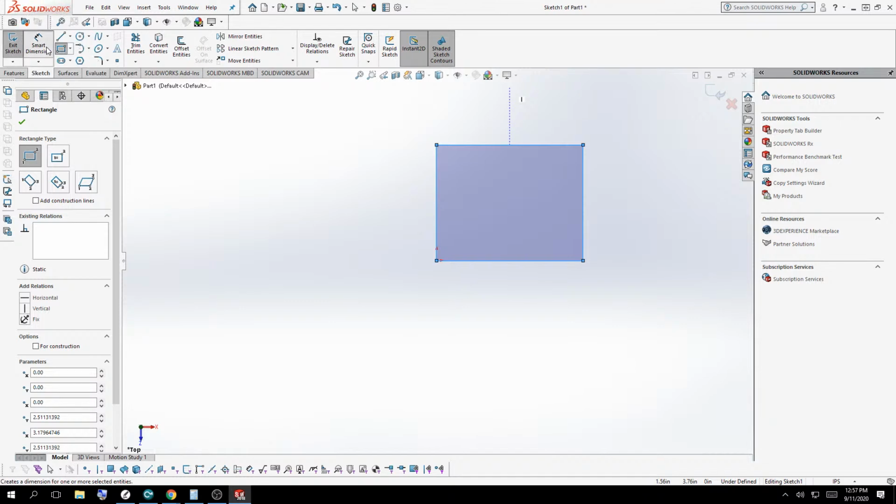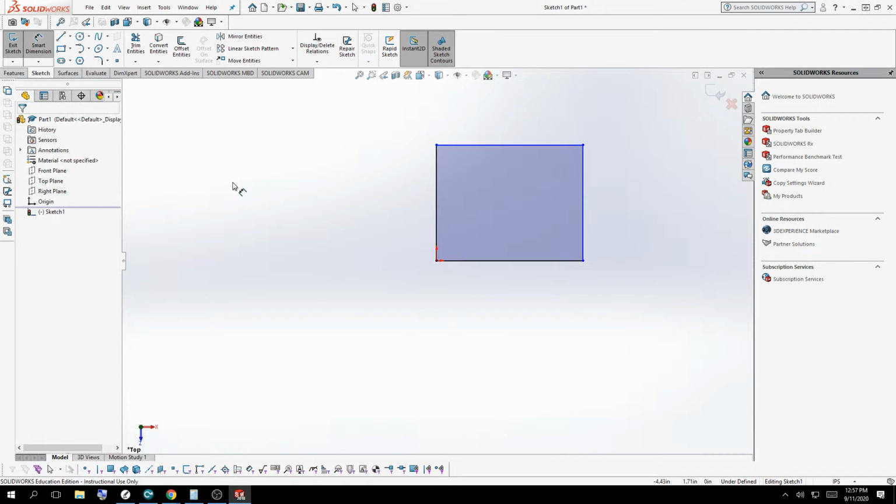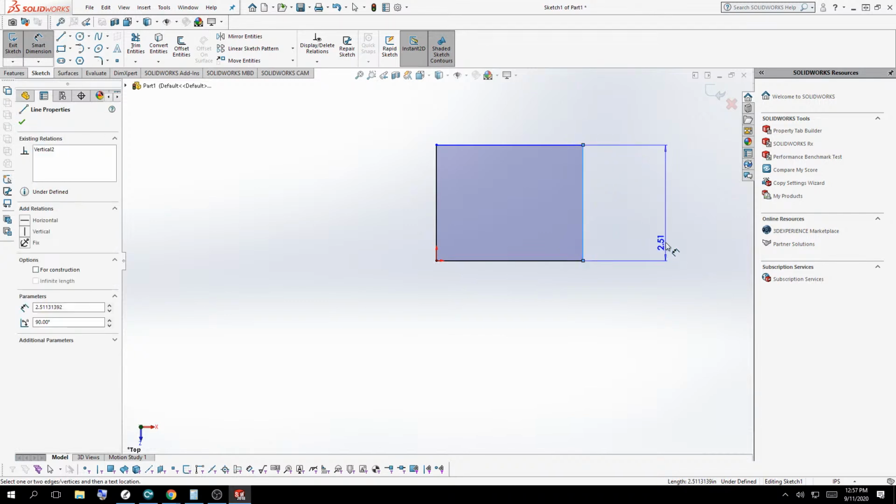So I want you to click Smart Dimension, single click, and you're going to notice your cursor goes back to the arrow cursor with what looks like dimension and leader lines with arrowheads. And what we're going to do is pick two perpendicular sides to create measurements. If you notice, when you hover your mouse over the geometry and go to the edge of the surface, you'll see that it's orange. When you click on the orange surface, remember we are clicking and releasing, your mouse will then be tied to the dimension number, the arrowheads, the leader lines, and the dimension lines.